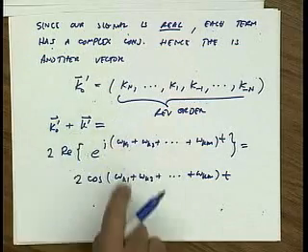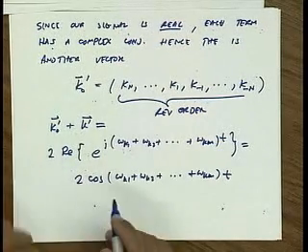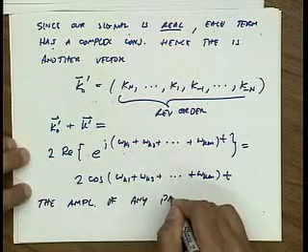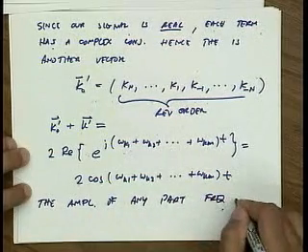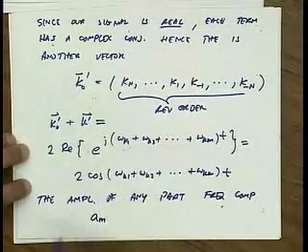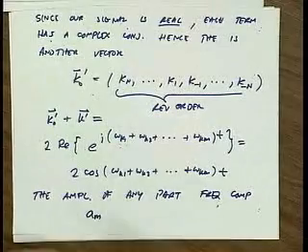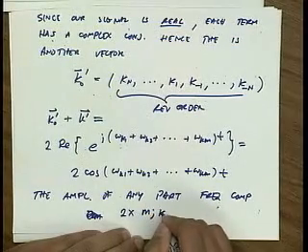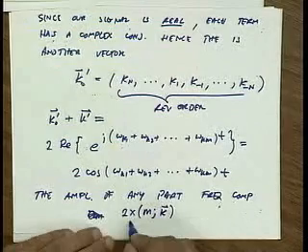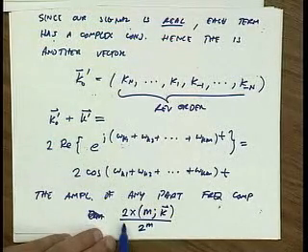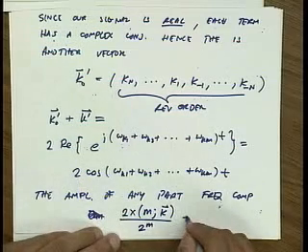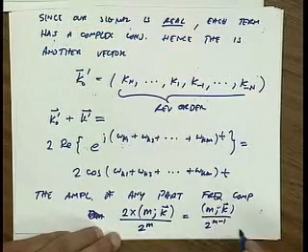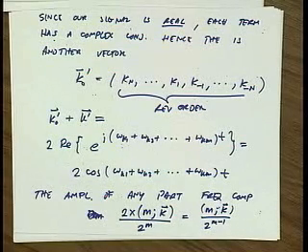And I know exactly how many different sums appear, so the amplitude of any particular frequency component is AM, right? If I'm doing a power series, let me not write AM, let me just keep it general. 2 times this coefficient mk, this multinomial coefficient, divided by 2 to the m. This factor 2, of course, just comes from here. So in other words, the amplitude is mk over 2 to the m minus 1. Okay?